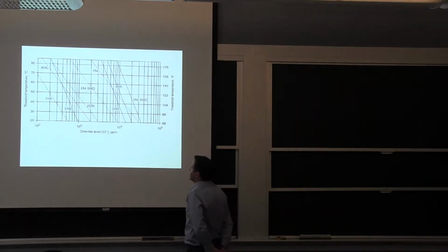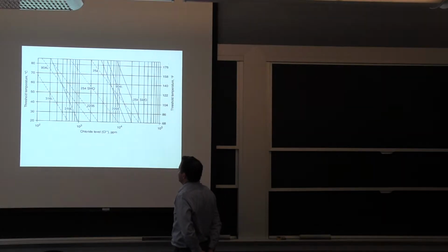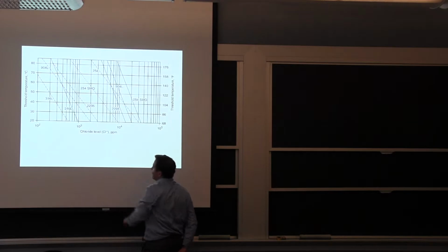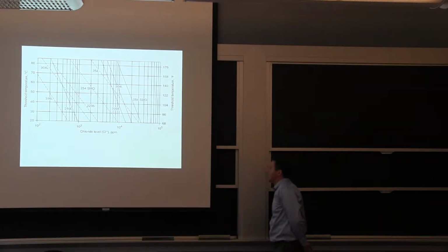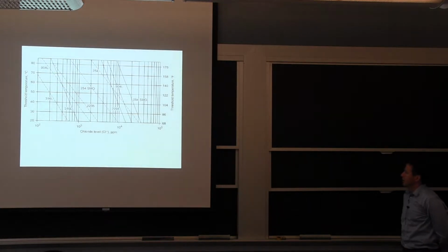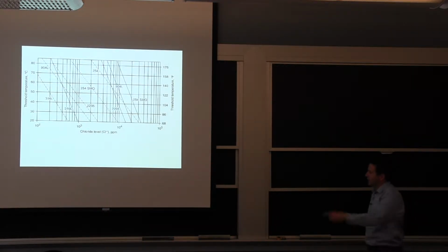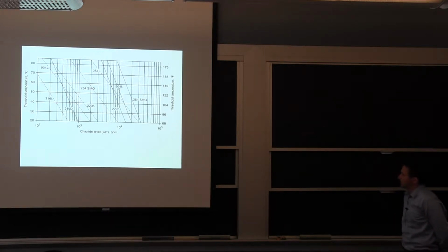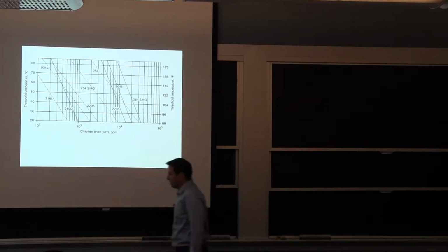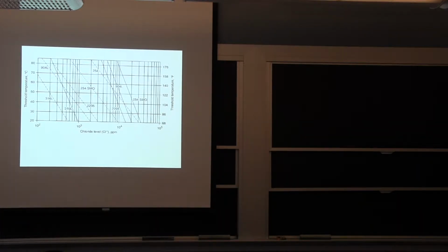Seawater will get you in the 10 to the 3, I believe, 10 to the 3, 10 to the 4. There's a lot of salt in water. So if you have stainless steel in water, it's likely to start pitting if it's just a standard grade, which was the 316 we discussed, or lower grade. So in the stainless steel family, 316 is normally considered a good grade.